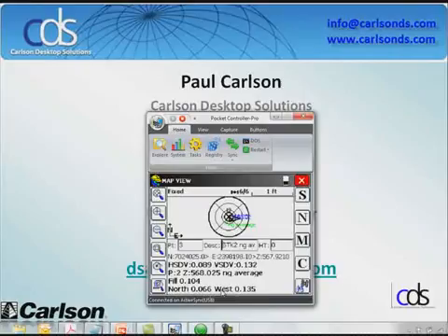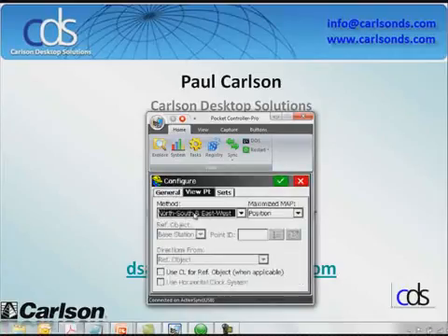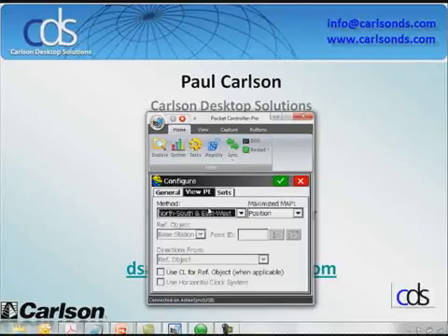I'm west of it. If I don't like how that's displayed, I can go into the configure, the C for configure, and I can view points, and I can change the method: in, out, left, right, north, south, east, west. With my GPS, I keep a pole clamp that has a compass on it, so that I always have a compass, because even though I know the sun rises in the east and sets in the west, I still need help sometimes. So I can control how that appears.